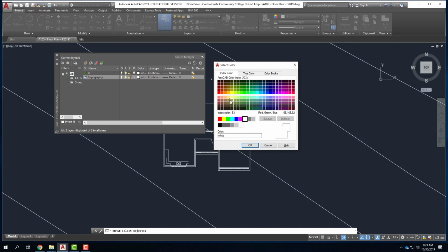If you work in a firm and you work on AutoCAD long enough, you start to see the drawing with line weights based on color, assuming that it's consistent. Now the problem is all firms aren't consistent. They don't all use the same colors, so things change depending on who you're working for. So in this class, and while you're in school, I would encourage you not to try to assign line weights by color, because when you go to work for a firm, they're going to tell you this is how we want to do it. So I caution you against it.